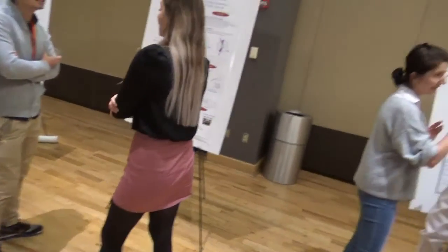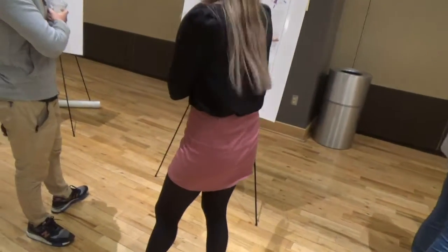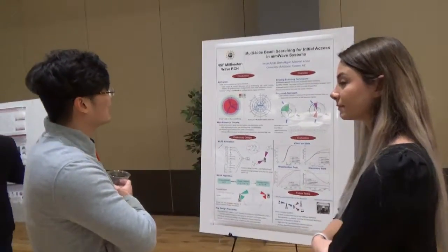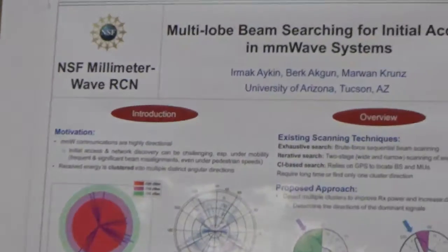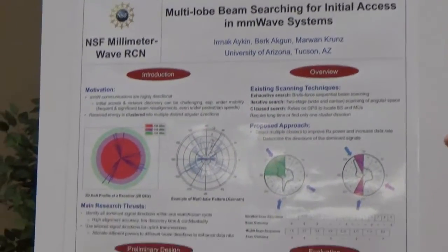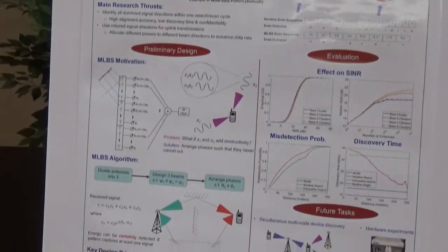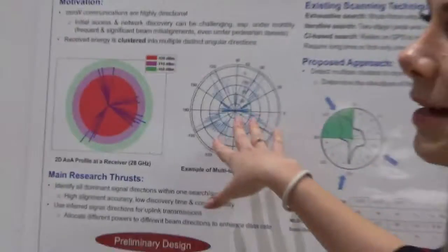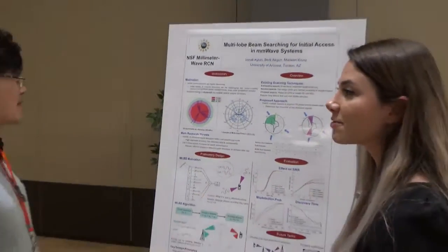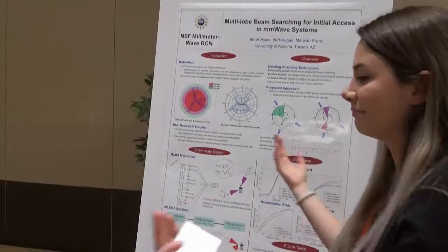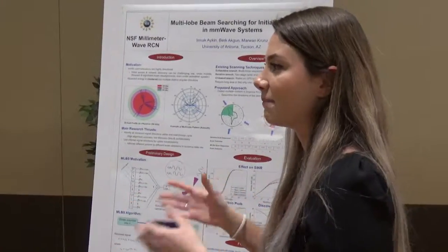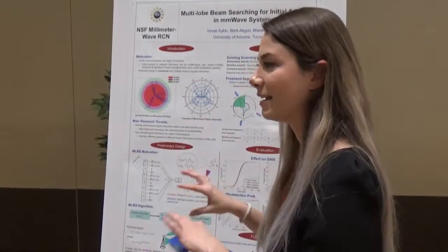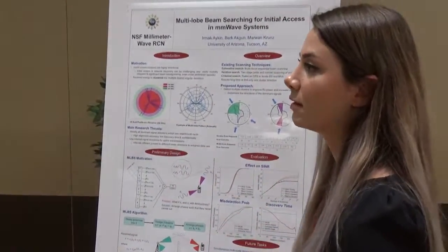Great. Here? Yeah. The beam is just like omni. So no matter what you do, it's omni. Exactly. Theoretically, you can get a nice multi-lobe pattern that looks like this, but when you look at actual measurements, actual patterns, they look like they have a 60-degree beam width or so. So it's not very likely that you'll be able to design those nicely separated multiple main lobes that we're looking into.